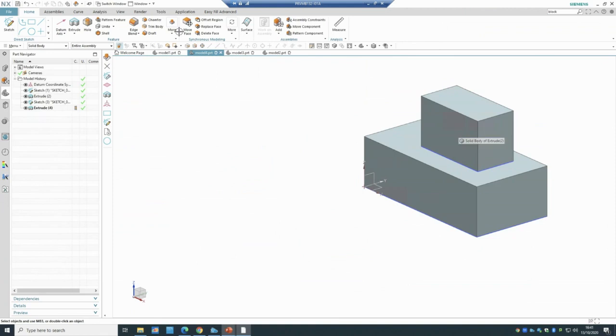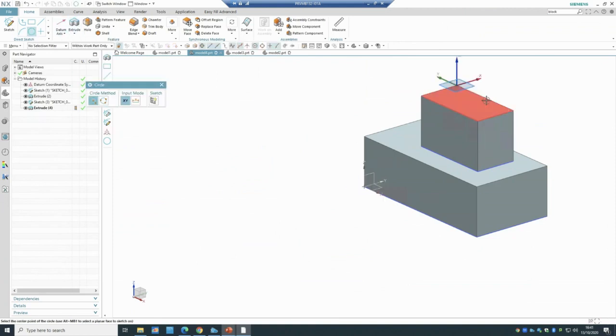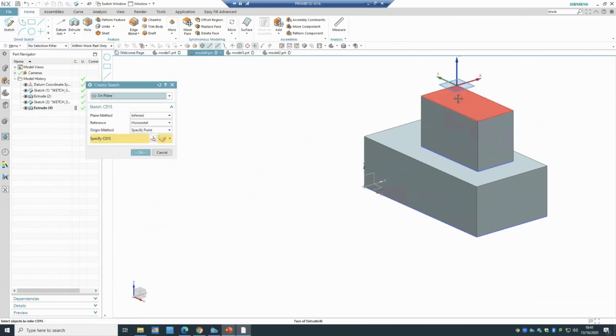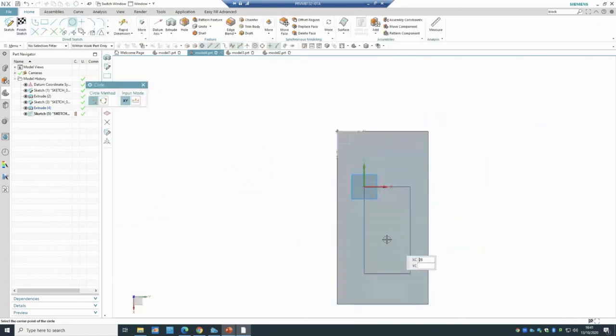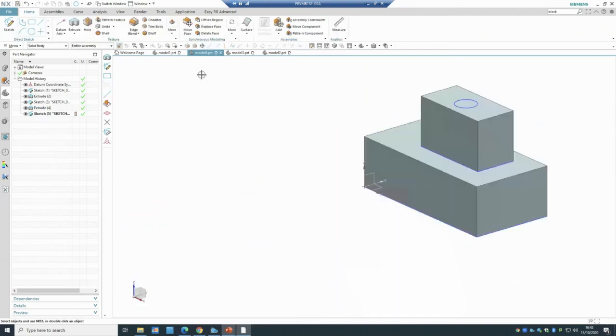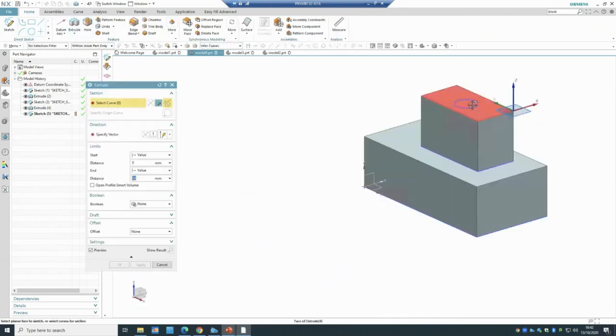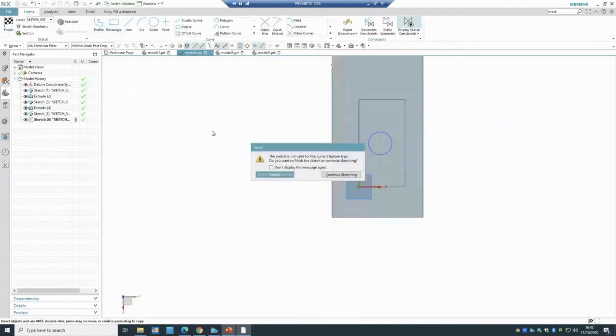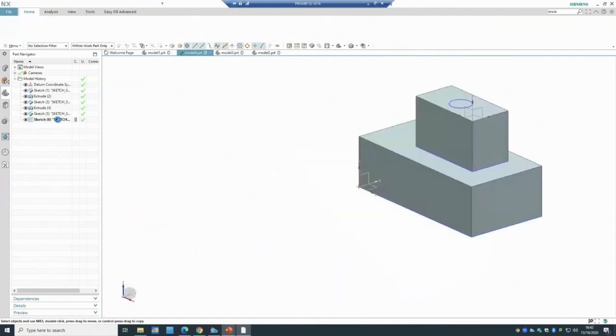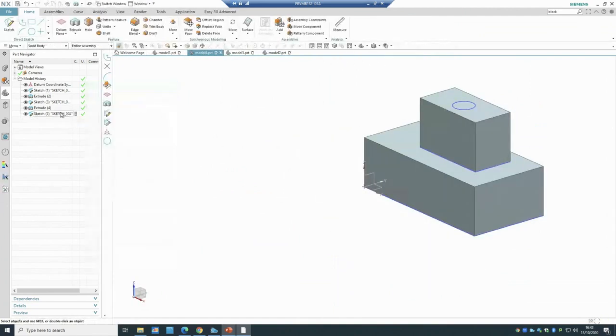Okay, so I'll repeat it one more time for you. Let's say I'm gonna do a sketch on top of this one. So I will go to the sketch, pick that plane, and click OK. Let's make a circle this time. Okay, and I will finish the sketch. Sorry, let me finish this one. I will use that as the sketch, which is this one. So we extrude that.